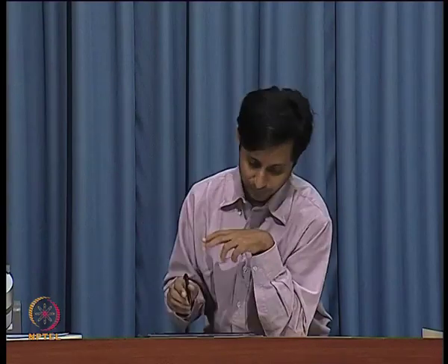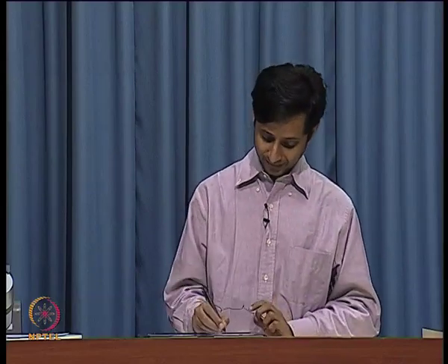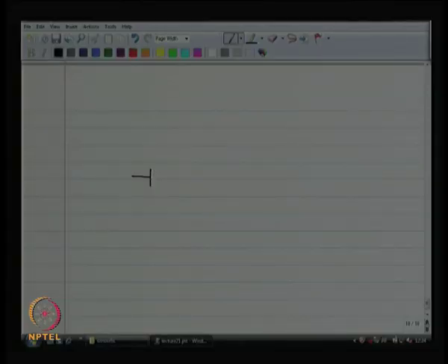Now, after all this, what do we do? What is an acceptable design? So, anything is acceptable as long as the noise figure is low. This is the catchword. Now, one of the interesting strategies that people use is they put an inductor and degenerate the source.